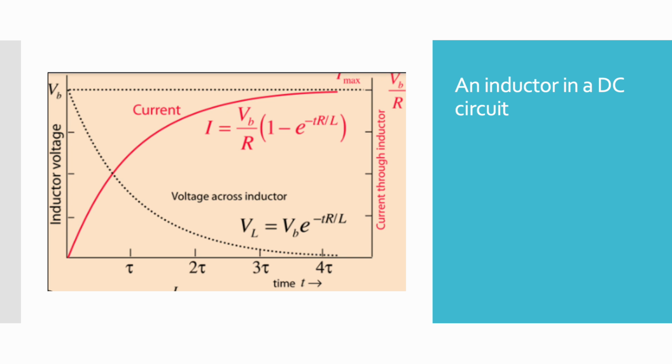When the power source of the circuit is turned off, the inductor again opposes the flow of current, and the discharging magnetic field induces a voltage in the opposite direction, as stated by Lenz's law. This creates a spike in voltage.